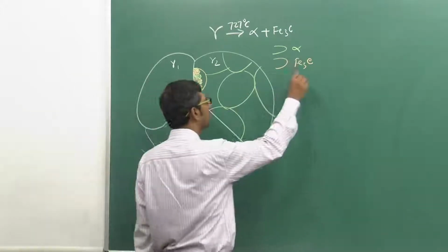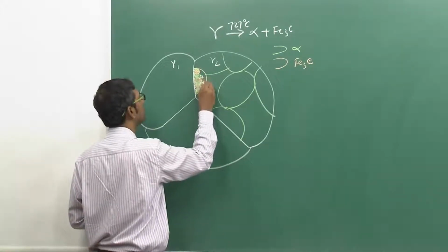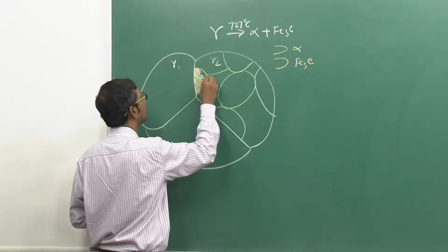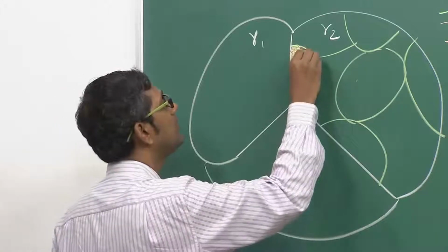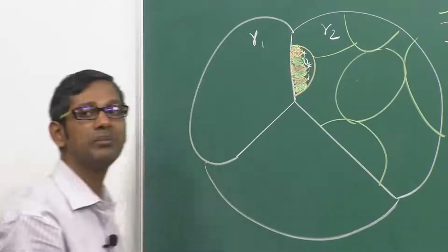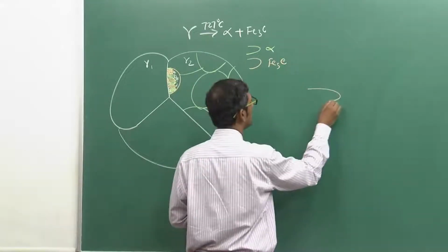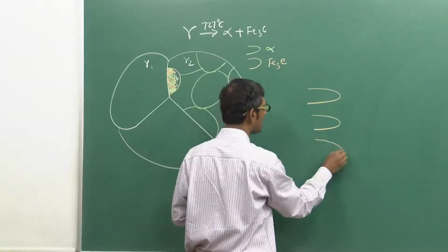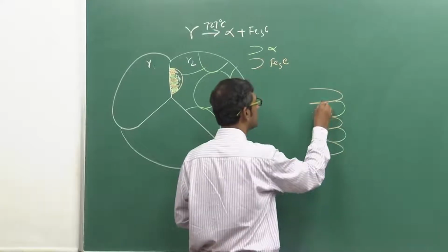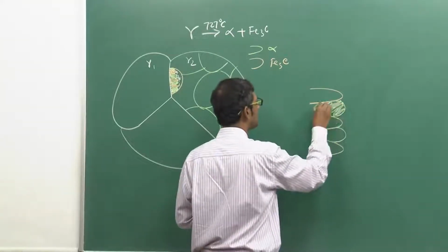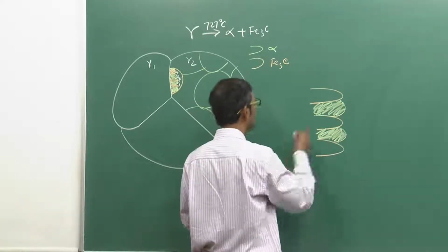So, it is very clear that the carbon is diffusing along this boundary, from alpha to Fe3C, and also from the major part of the gamma grain in front of it to the Fe3C. That means the lateral diffusion of carbon is what is playing the role. So, if I have to draw it properly, the whole thing, lateral diffusion of carbon: these are the cementite lamellae, and in between I draw the alpha lamellae, okay. So, this is alpha and this is also alpha, and these are the cementite.